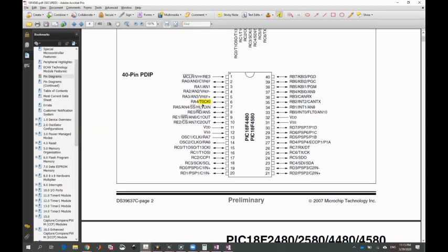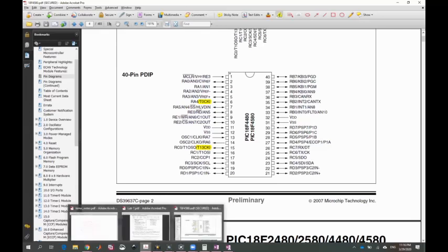So this is for timer 0, and for timer 1 we have the timer 1 clock pin. Timer 1 and timer 3, both of them have the same clock pin. So if we select timer 1 or timer 3 in counter mode, they can count pulses on this pin, the T13 clock pin. The pulses can be either a rising pulse or a falling pulse.